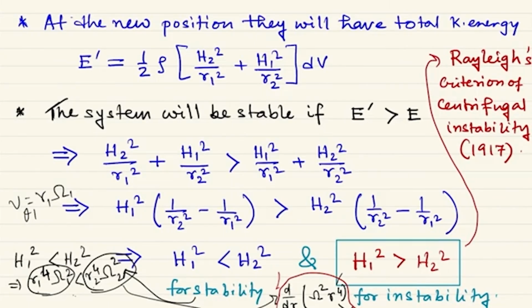So in this lecture, with a very simplistic analysis, not much formal work, and for very simple cases (axisymmetric, only azimuthal flow, steady condition, incompressibility), we concluded that not every differential rotation is self-sustained. If Rayleigh's stability criterion is satisfied, then once a differential rotation is established in a system, it will be there and will not decay.